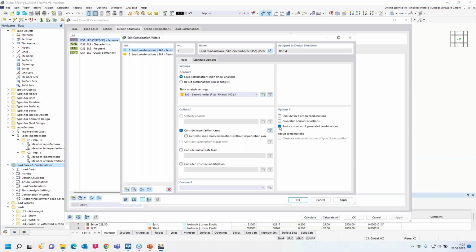I can explain it with a simplified workflow. All load cases are calculated individually, based on the calculated values of internal forces and moments, deformations and reactions. You get 2 groups of load cases for each location. One group contains the load cases with positive values, and the second group includes the load cases with negative values.